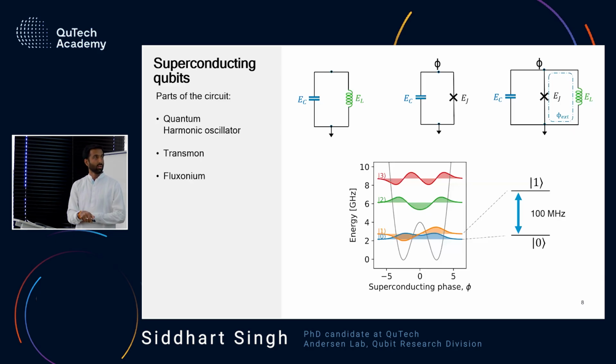The 0 ground state is generally the symmetric superposition of the clockwise and anti-clockwise current flowing in the loop here in the circuit. And the 1 level is the anti-symmetric superposition of the clockwise and anti-clockwise current flowing in the loop. You can say that now you have introduced 3 channels. This can lead to more losses because you have introduced more channels or more sources of loss.